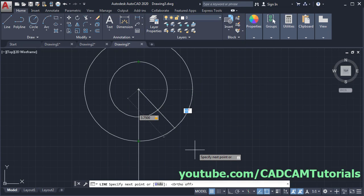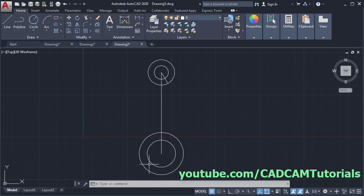So give here angle of 60, enter and enter. Then same way we need to create line below. What we can do, we can also mirror this line. Click on mirror, select this line, enter. Then first point of mirror line will be the midpoint of this line. Click there, take your cursor on the right side, ensure that this line is straight, click and click on no.